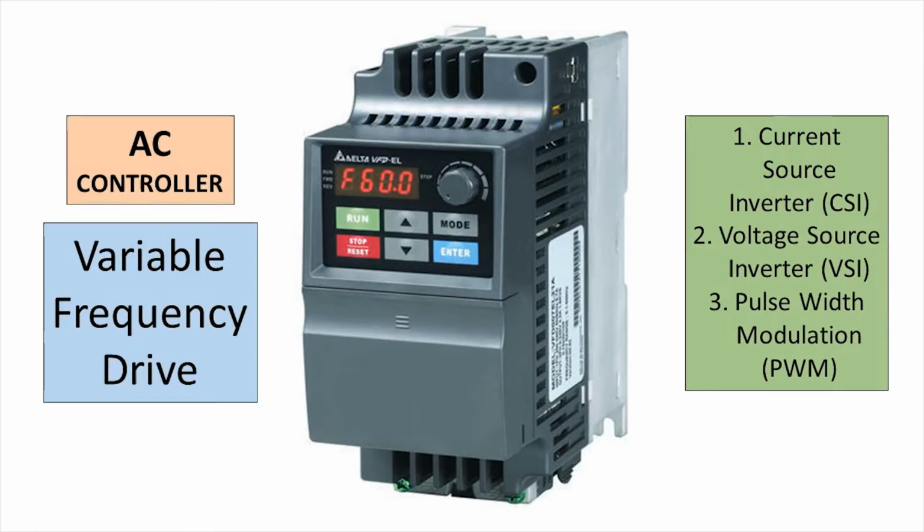The VFD is a particular kind of adjustable speed drive that is used to control the speed of an AC motor. In order to control the motor's rotational speed, a VFD controls the frequency of the electrical power supplied to it. Adding a VFD to an application allows the motor speed to be adjusted in accordance with the motor's load, ultimately saving energy.